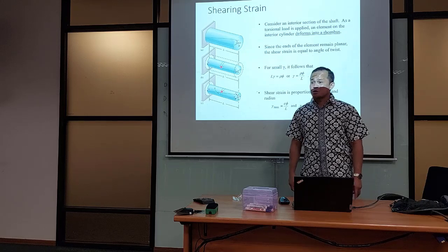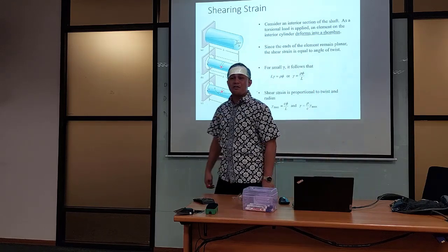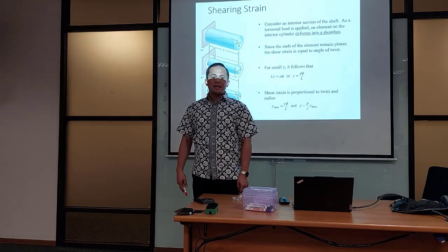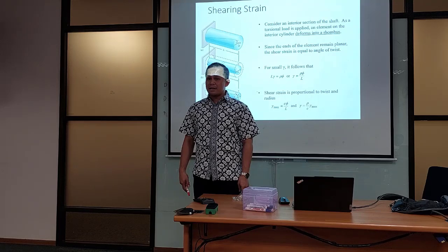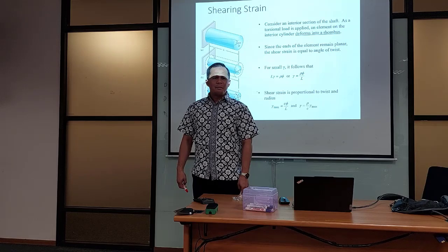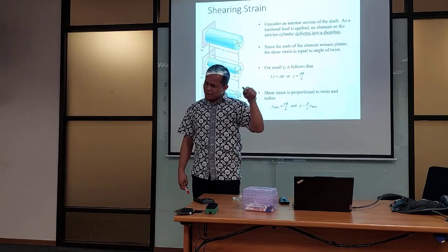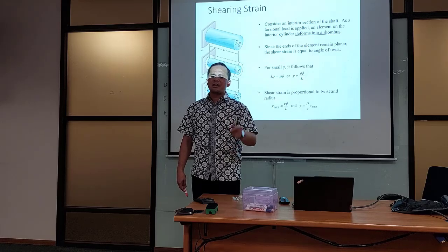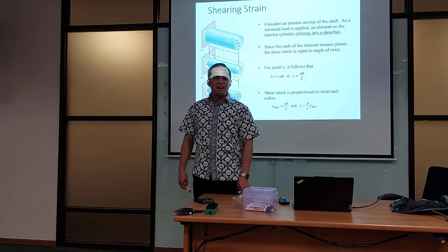So the most stressful position of a shaft under torque is at the surface. So if you are applying the torque too big, where will be the first location to break? Surface. So if you see your shaft crack at the surface, you know that is of course because of the torque. If you see your shaft crack in the middle, do not even think it is because of the torque, because the torque is minimum in the middle.